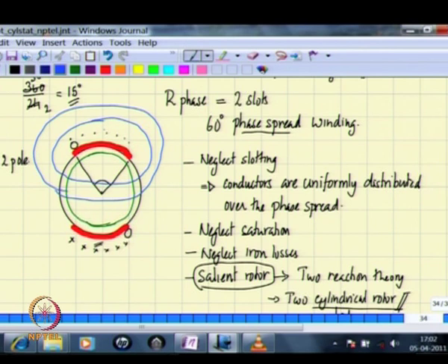We see that irrespective of what flux line you take, maybe even something that goes here, as long as the flux lines cross the air gap in this region, the net amperes enclosed by this loop always remains the same.